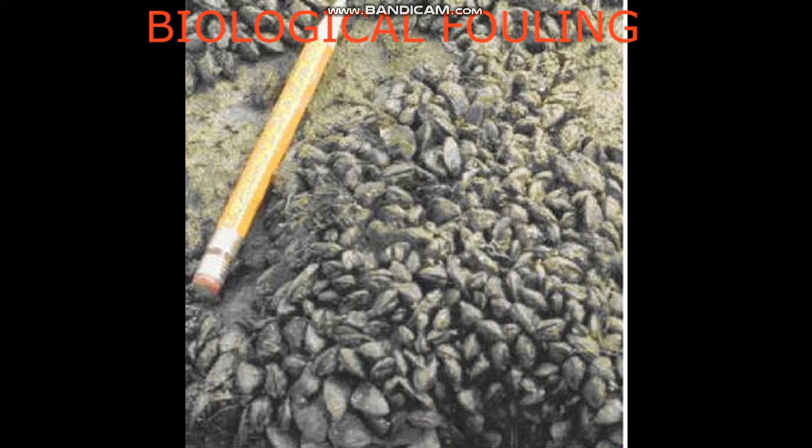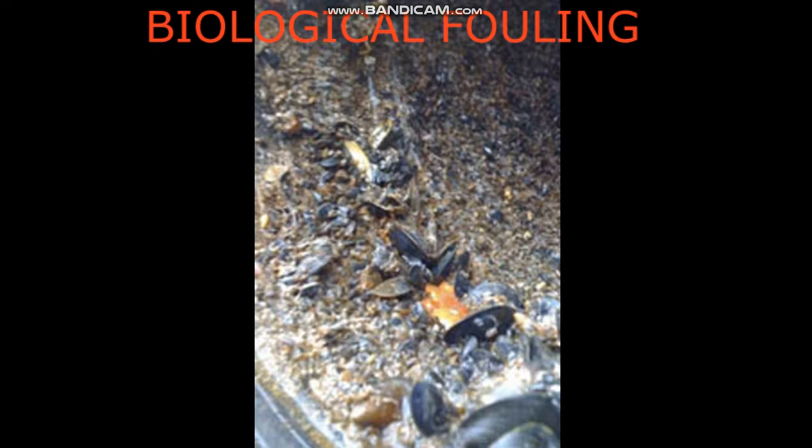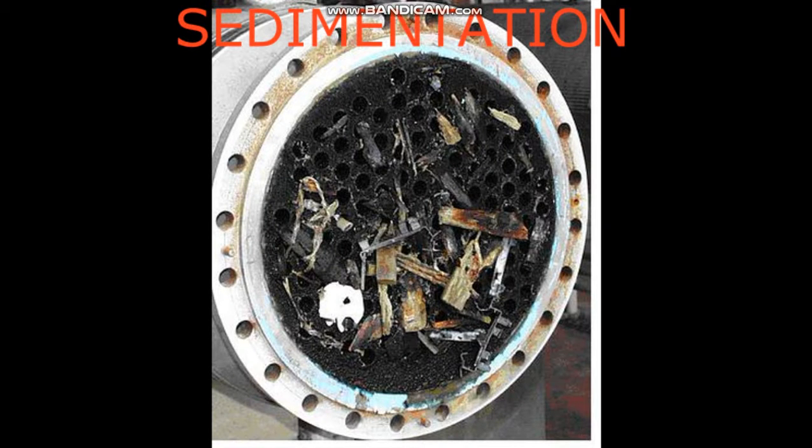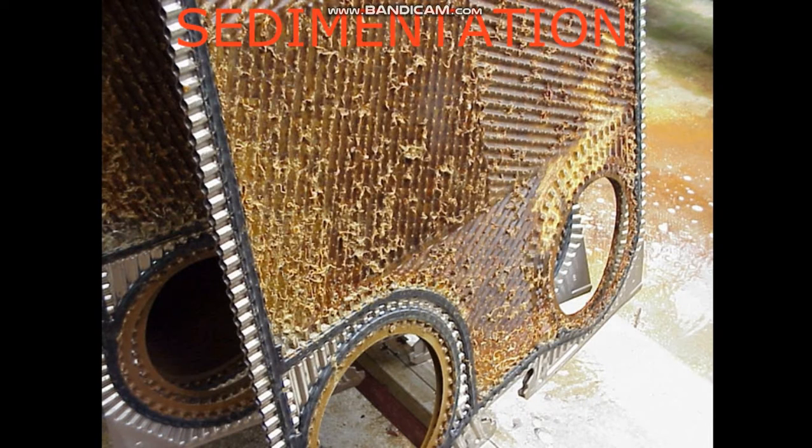Biological fouling is common where untreated water is used as a coolant stream. Problems range from algae or other microbes to barnacles. Sediment fouling occurs when particles in the solution settle and deposit on the heat transfer surface. Like scale, these deposits may be difficult to remove mechanically depending on their nature.